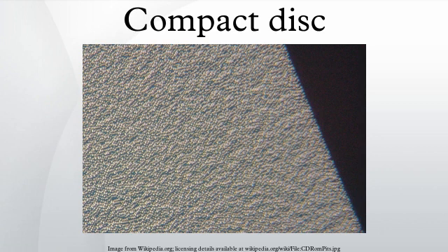A small amount of lacquer is applied as a ring around the center of the disc, and rapid spinning spreads it evenly over the surface. Edge protection lacquer is applied before the disc is finished. The disc can then be printed and packed. Manufactured CDs that are sold in stores are sealed via a process called polywrapping, or shrink wrapping. The most expensive part of a CD is the jewel case.